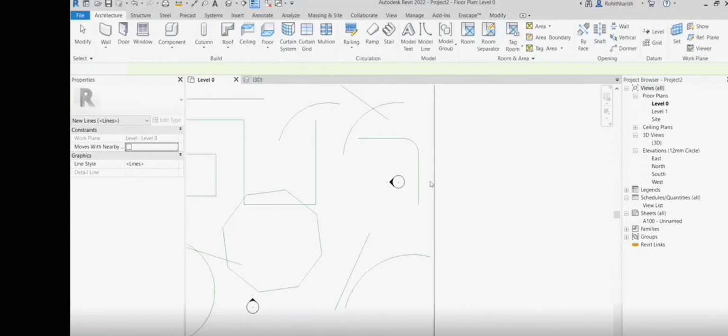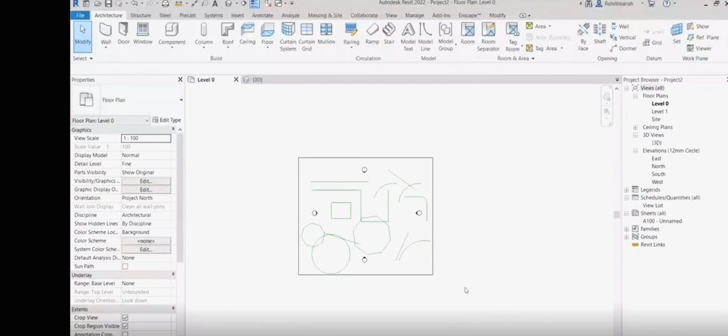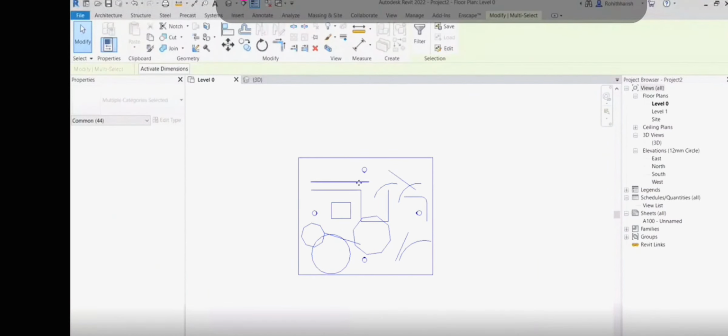We have selected everything, maybe the elevation markers that we have made, the crop window that you can see, and along with that, whatever we have drawn, everything is being selected. But after selecting everything, I want to delete only the elements that I have created using the line command. So how am I going to do it? For that, we have a solution called selection filter.